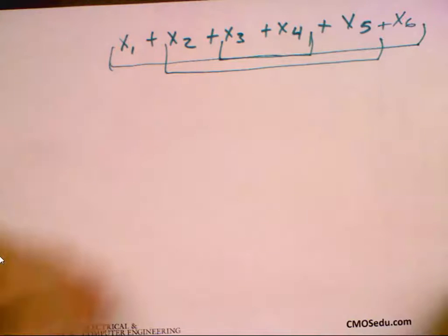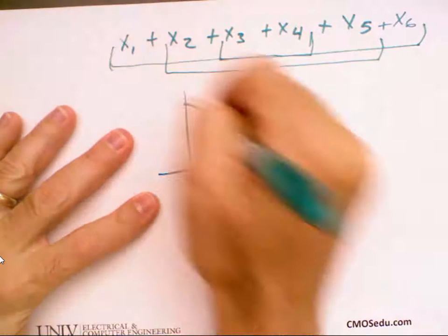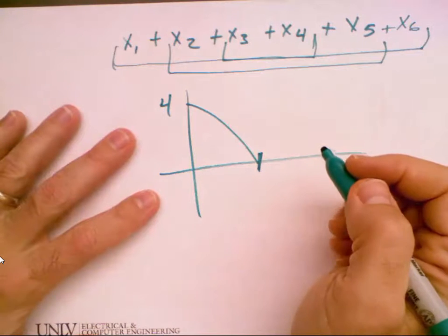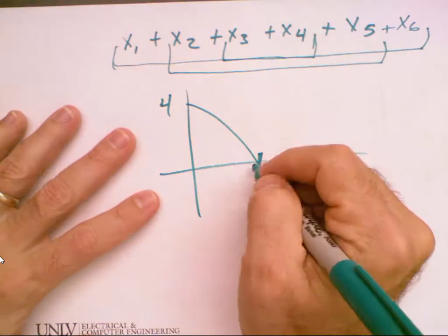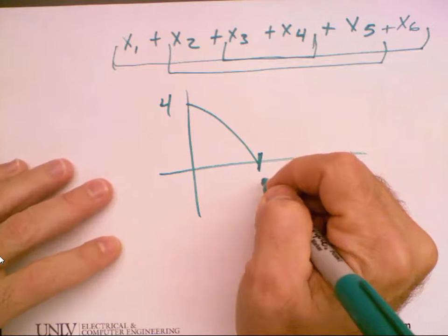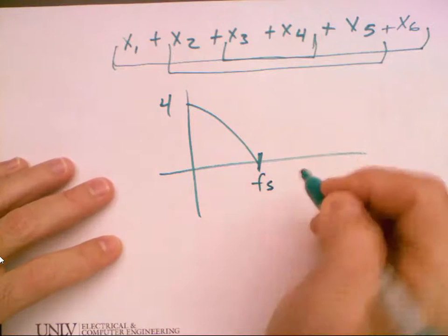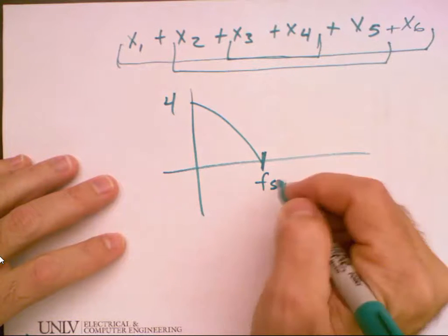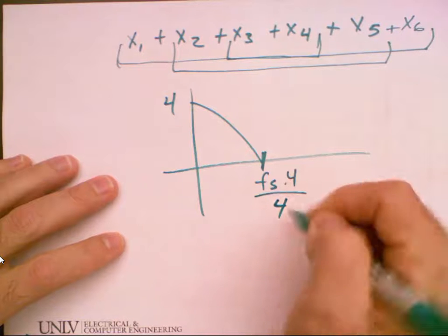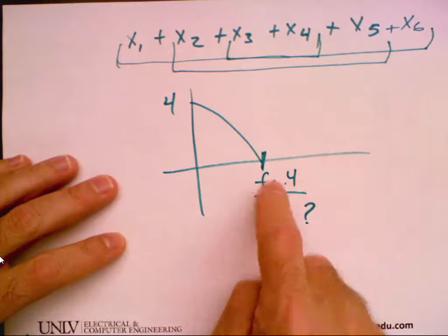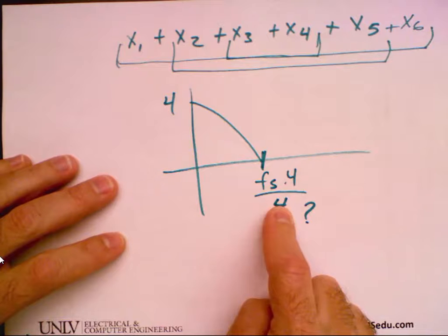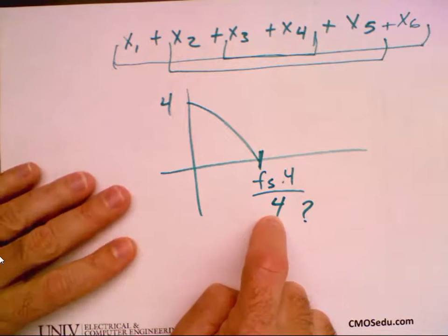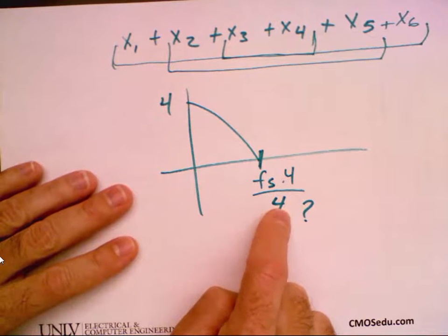Okay, but the big difference is, so I get my 4 here, it's averaging. This is not at, it's going to be at f sub s, I think, is the right one, because it's 4 times higher. So it's not a frequency of 4, I'll put a question mark there. Instead of f sub s over 4 for an averaging of 4, it's 4 f sub s over 4 because of the equivalent higher speed feedback. Does everybody follow that?